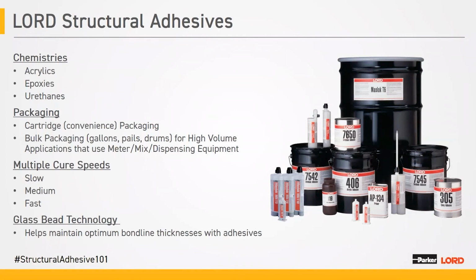Many of our products offer multiple cure speeds, so they have a consistent adhesion and consistent physical properties across a wide range of different open times. So we may offer a 3 to 5 minute open time for a faster product, and maybe a 60-minute open time for a slower product. Glass bead technology is something we offer in some of our products. This helps maintain the optimum bond line thickness with adhesive and prevents too much adhesive from being squeezed out.